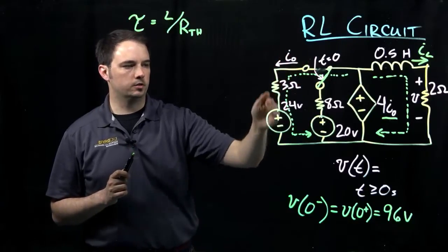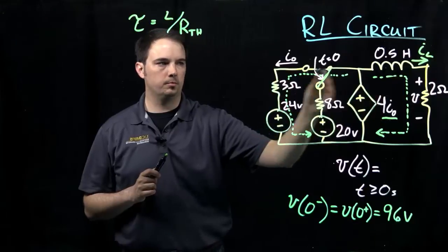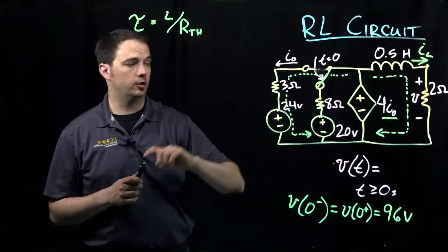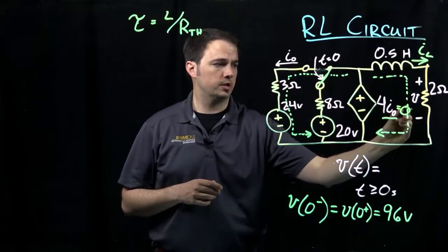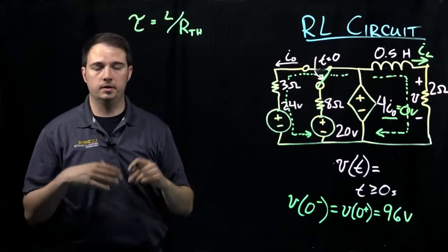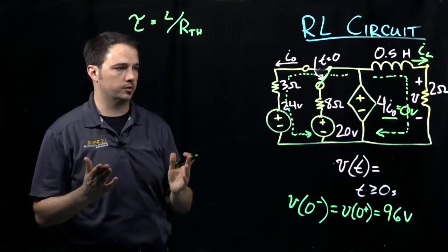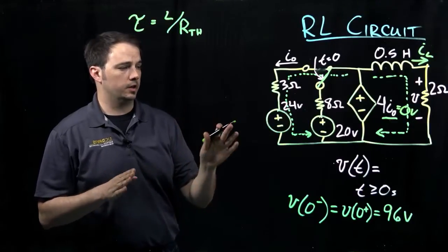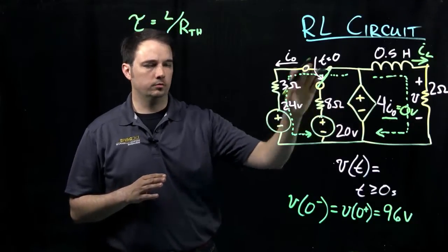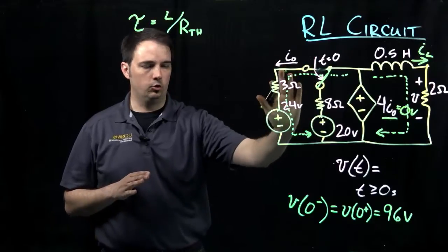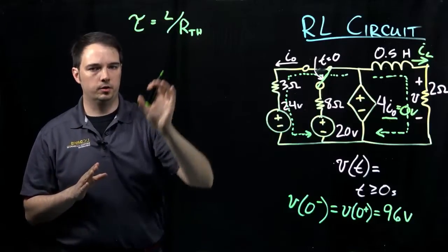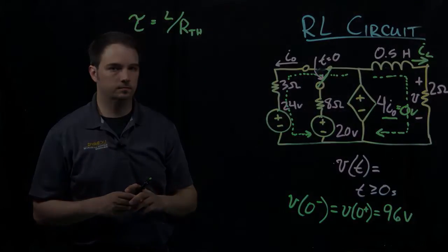Because this part of the circuit is now basically disconnected from the rest, I could have no current flow in this branch here. And therefore, if I have no current flow here, I know that this voltage just has to go to 0, which, as we know, a 0 volt difference across any given element is basically the same thing as having a short circuit there. So with that in mind, let me take a quick minute to redraw the circuit to best describe what we're looking at, with the fact that I can basically ignore what's going on here because that's been disconnected, and I have a short circuit here. And then let's think about how we come up with this Thevenin equivalent resistance.